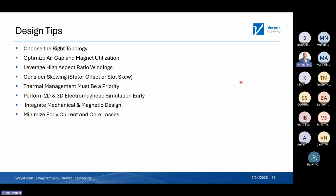Also, the other idea is to leverage high aspect ratio windings, because flat windings perform better, since that's how the flux goes from rotor to stator in these configurations. As you saw earlier, just offsetting or slot skewing will reduce a lot of things like cogging or torque ripple, but we also saw that it's aiding the total torque, which is excellent. You don't have to add extra materials, rather you just position them differently.